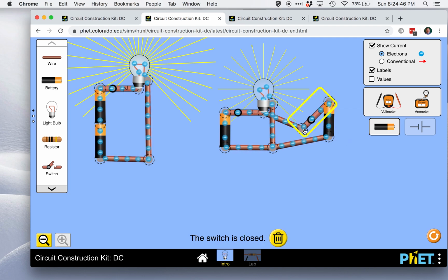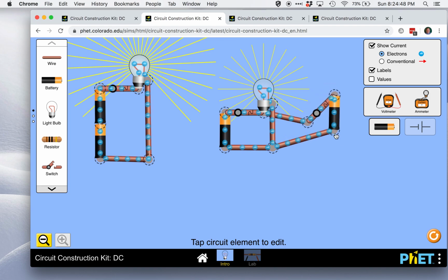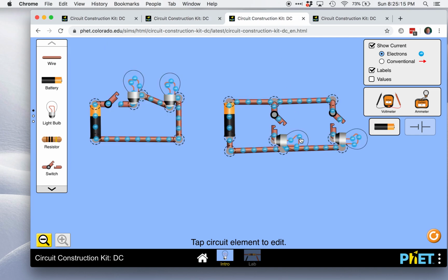There. Now we have both batteries pumping charges, half of the charges that go through the bulb. So you get the same brightness of the bulb as a single battery, but both of the batteries actually do half as much work. So the advantage to wiring batteries in this fashion is that the batteries last longer. And the only place in my house where I know I have batteries wired in parallel like this is in my wireless mouse that I use with my computer, and that means I have to change the batteries in that half as often. The third simulation asked, can you light multiple bulbs?